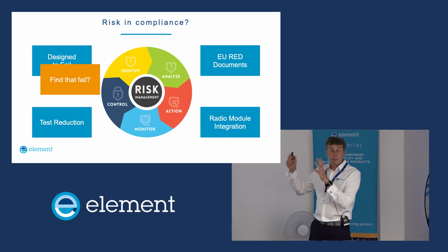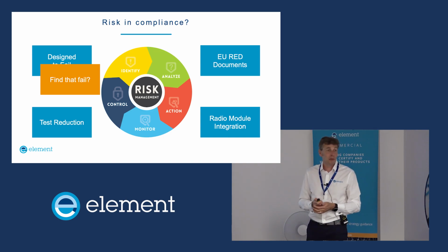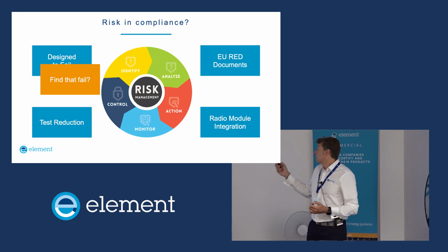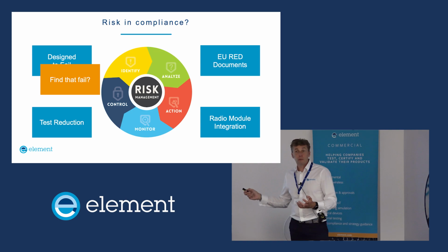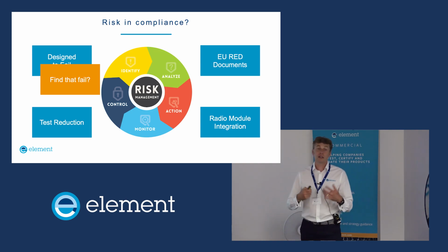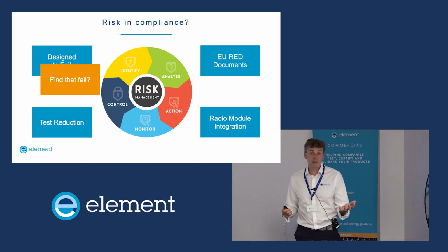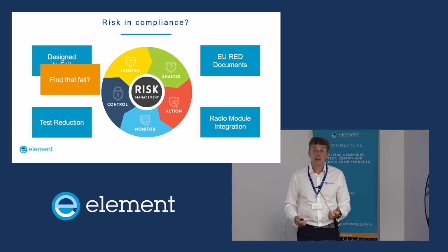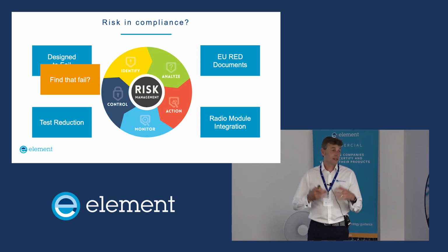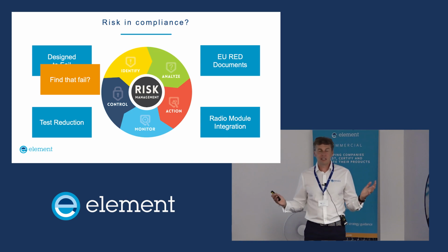So your product might have some failures within its capability, and it's the responsibility of you as a manufacturer to check that that isn't going to happen. With Europe, the Radio Equipment Directive, in your documentation, you have to document everything you've done as part of your risk assessment to explain your compliance approach. And if market surveillance ever comes to your product because they want to audit it, or maybe your product causes some interference and somebody complains, or you get too many consistently bad reviews on Amazon or whatever, one of the first documents market surveillance will ask you for is your risk assessment, because they want to see which approach you took.